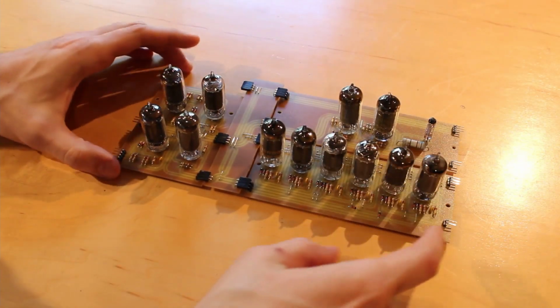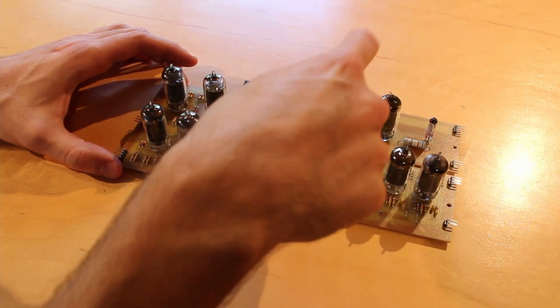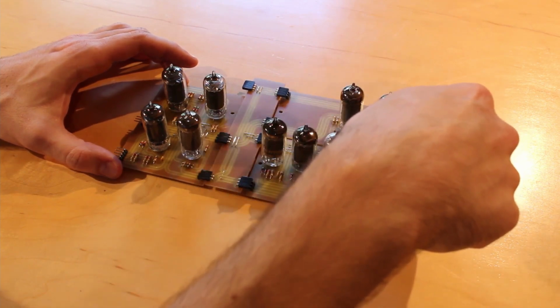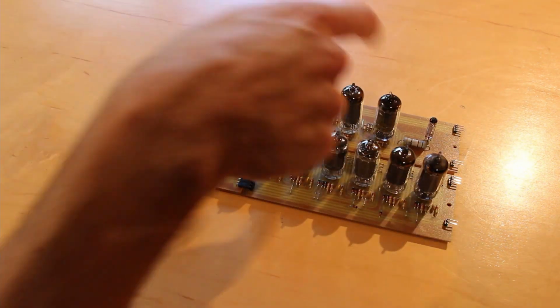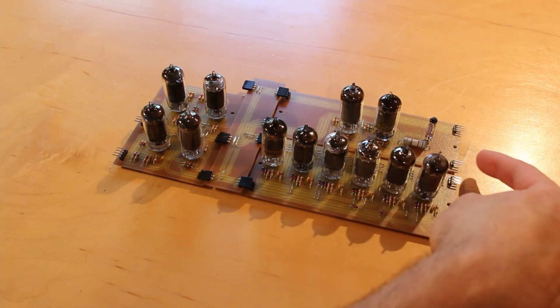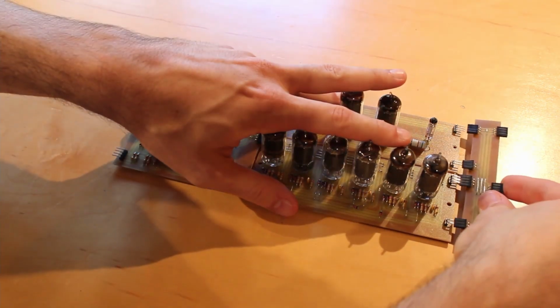All right, and so what this does is it takes the inverted output of the register, brings it in, inverts it, and then buffers it. And then this little VFD is our display that lets me know what is stored in the input enable register. But in order for this one to work, the output of the input enable register, which is here, needs to come over to the input over here. So I've got another board specifically for that.